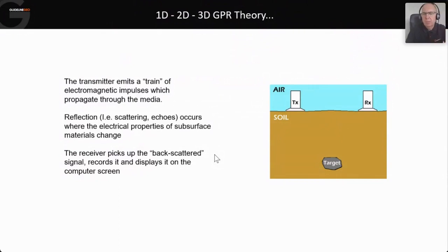What we're going to do with the system is launch the electrical signal down to the TX antenna, the transmit antenna, and that will generate a pulse of energy in the form of an electromagnetic wave, a radio wave in effect. And what I'm going to do just on the section here, this is a recording of what's happening on the receiving antenna. So we'll launch a signal and we start recording, and we're going to measure over time. So we send that signal out. That signal will start to expand outwards in a semicircular fashion because it's a shielded antenna.